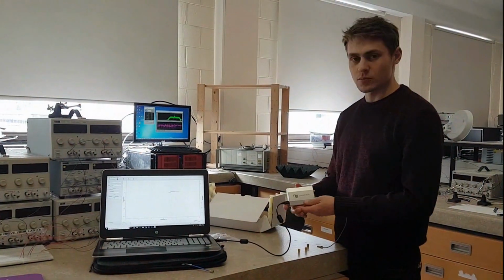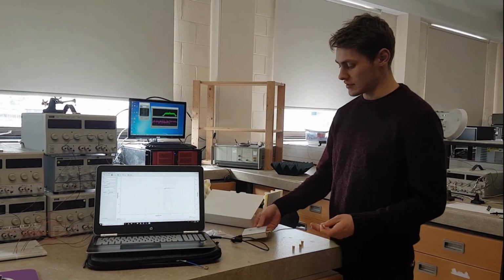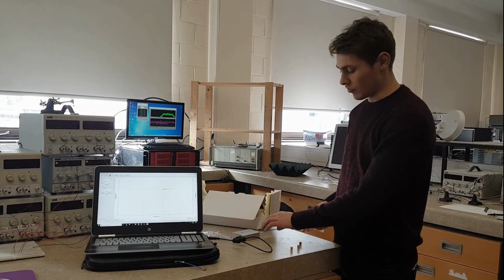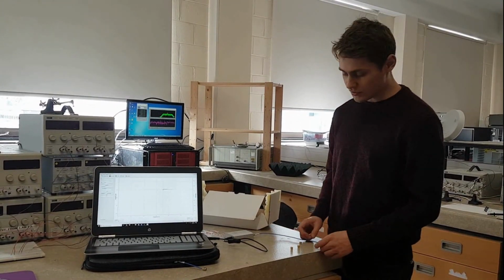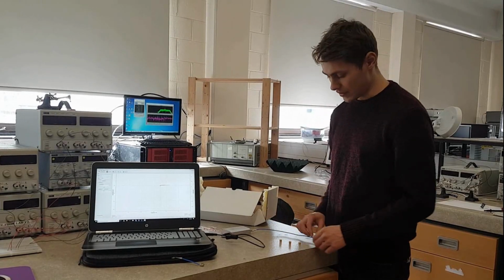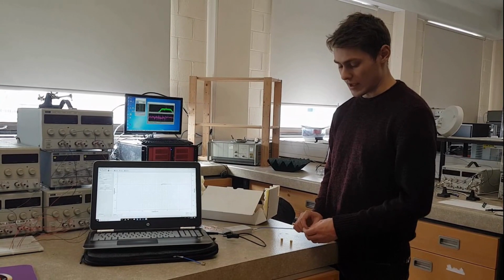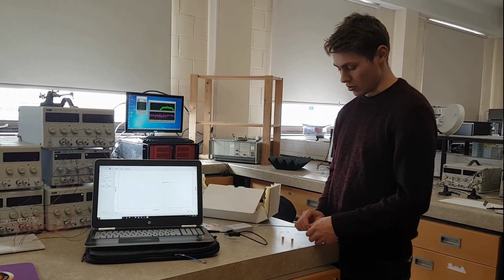Here we're using a small USB pocket VNA to measure the antenna. This is a one-port device, and as we've got a patch antenna, we need to do a calibration for an open, short and load. There's no need to worry about the through calibration. I'm going to do that just now, and then we'll display the results of the S11 reflection coefficient.